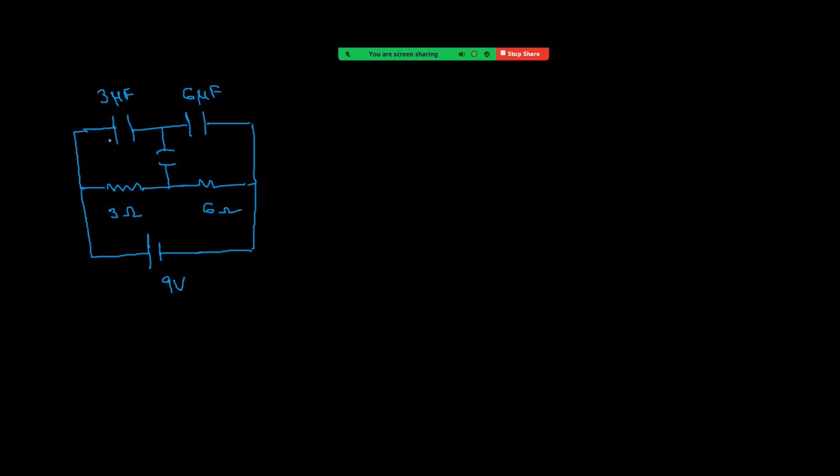These two are in series combination, so the effective capacitance will be 3 into 6 by 3 plus 6, which is 2 microfarad.